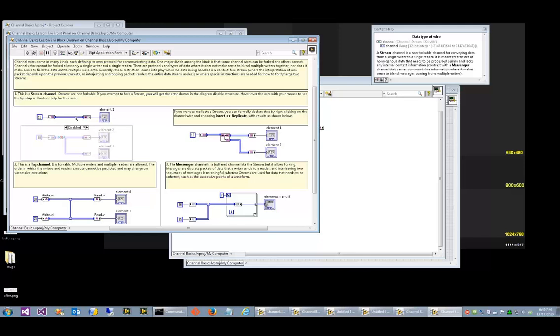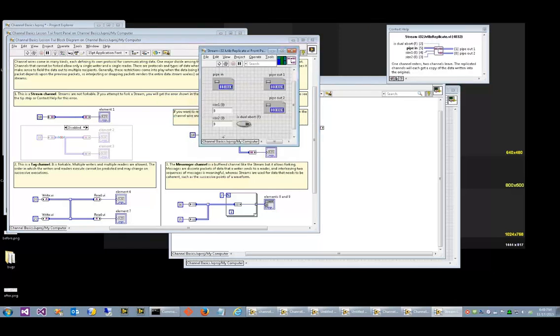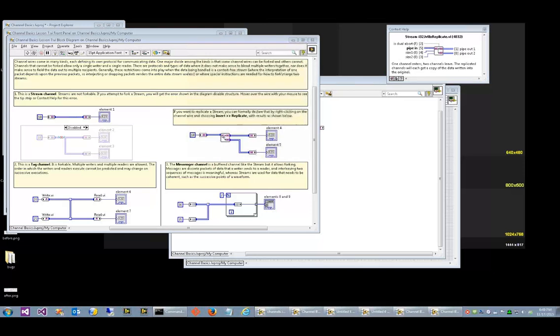I think his last comment was, how do you pass them to something that you cannot wire directly to? I assume he's asking, can you put it on a connector? Well, they're on a connector pane. That's what these sub-VI nodes are, like the replicate that we're showing there. So there's their connection on the front panel there. So you don't interact with them the way you do RefNums, and you shouldn't need to. Like I say, they connect into asynchronous call by ref nodes. If you're trying to do dynamic patching, that's how you make them dynamic, by choosing the endpoint that you're going to.